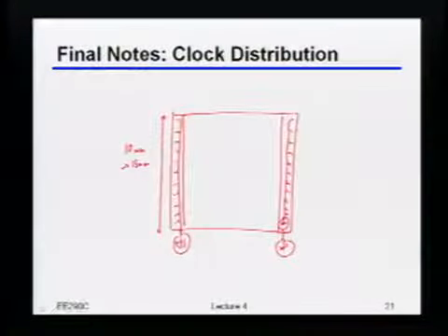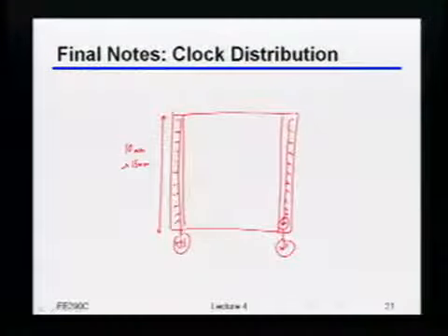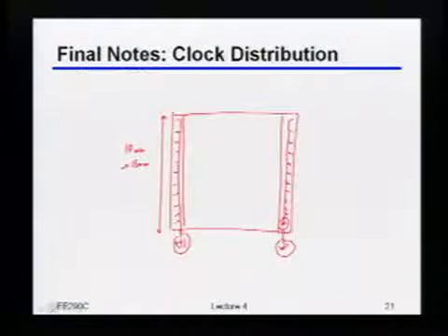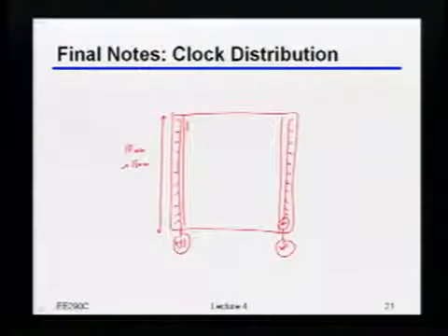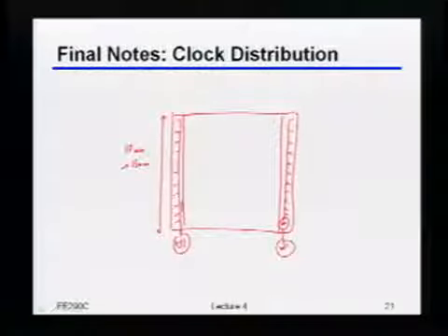With both of these, you have to be really careful with how you distribute those clocks. To cover about 10, 15 millimeters, you're going to pick up a lot of loss, even at the lower frequency of the crystal. That means you probably have to insert some buffers. Those buffers usually are sensitive to the power supply, so you'll very easily pick up quite a bit of jitter just from distributing that clock across that distance. There's also another trade-off, which is how much power it takes to distribute that clock. Doing it at the lower frequency seems more attractive because there's lower loss and lower CV squared F power paid.